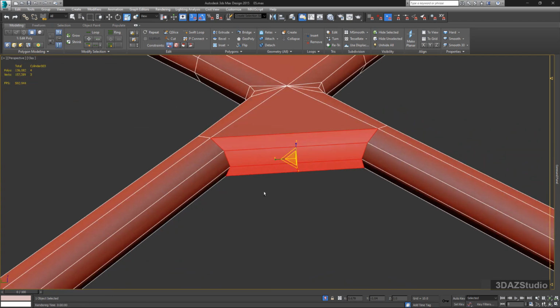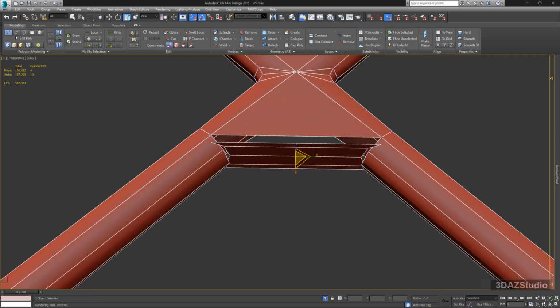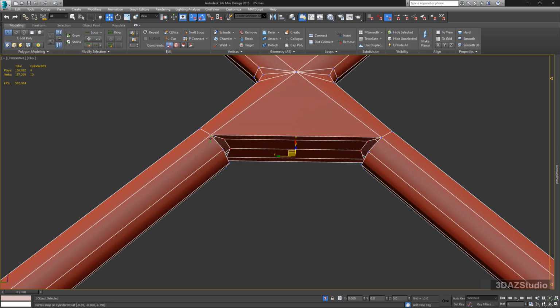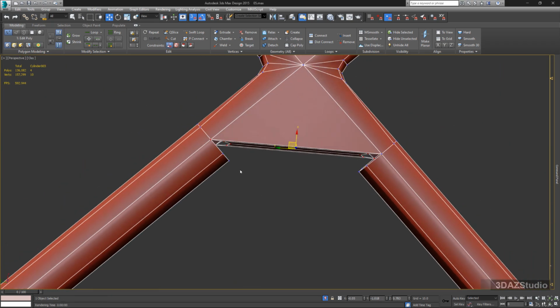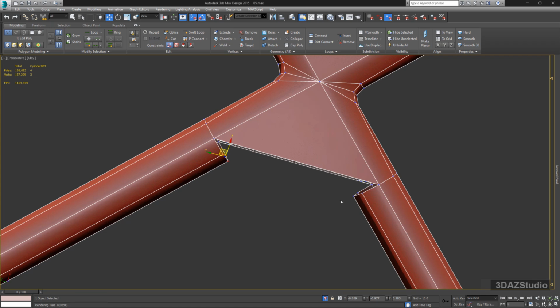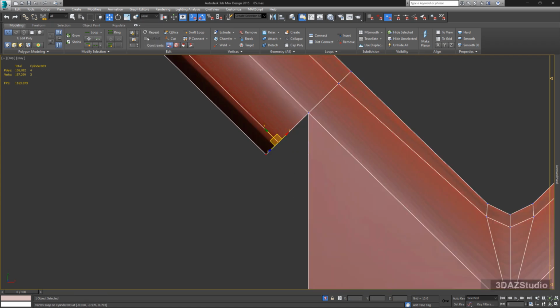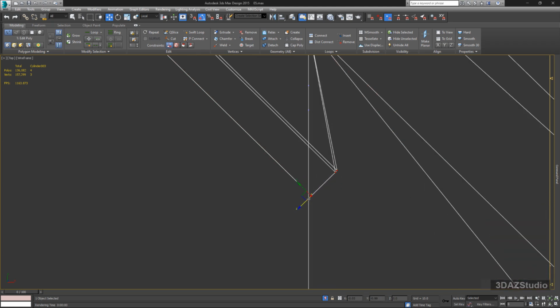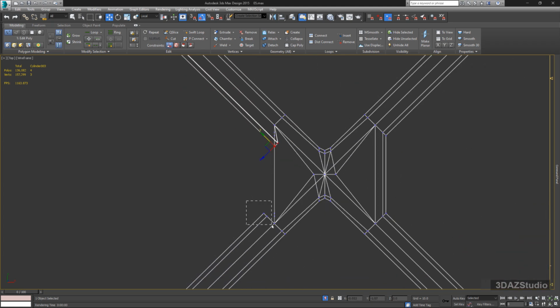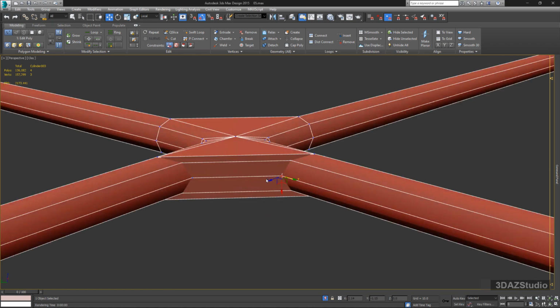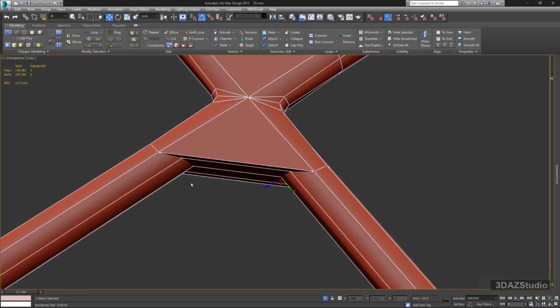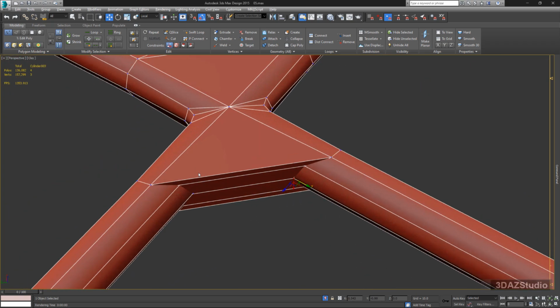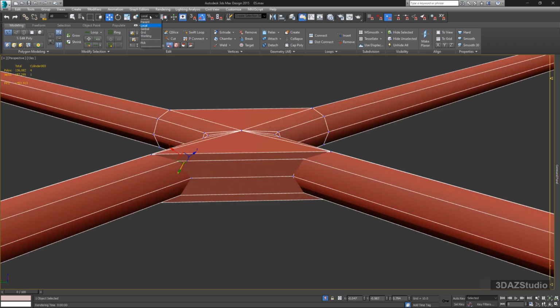To maintain the cylindrical surface while flattening the cap sides, we need to detach the cap sides into separate elements before flattening them. Use Snap to Vertices to reposition the flattened elements. Switch to local coordinates in the top viewport and extend the open edges until they intersect with the flat side. Then, switch to the perspective viewport, enable Constrain to Edges, and align the edge vertices to the flat surface.